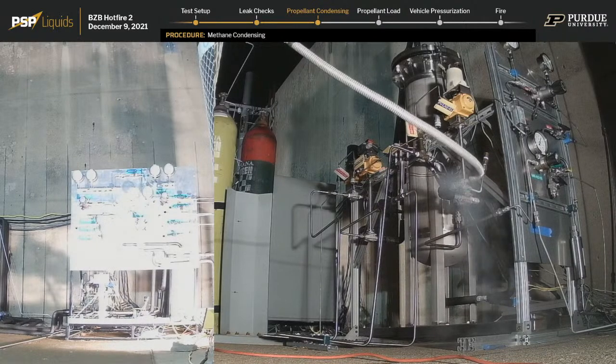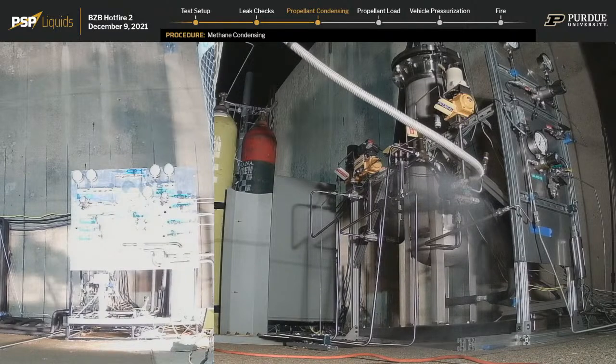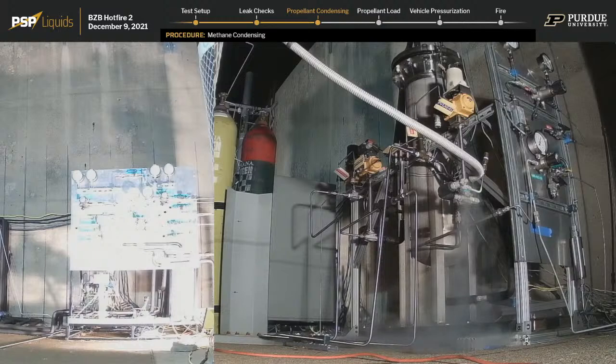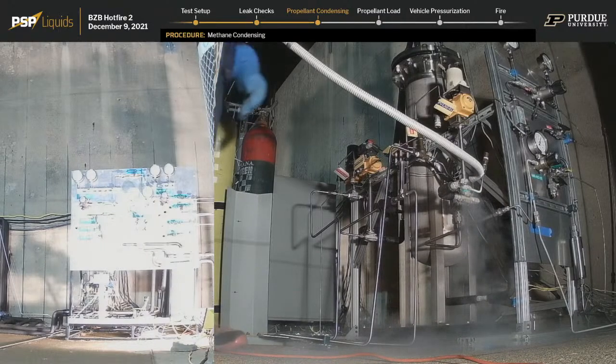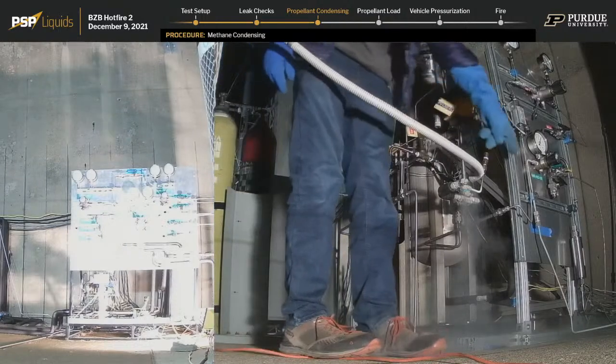Okay, we went ahead and opened PVLN201 to begin LN2 transfer to the condenser again. Believe you can hear it now. The LN2 flowing, hopefully not flowing out the dump valves anymore, but now we're seeing some of that ice forming and the clouds that we were expecting earlier. You can see the lines are turning white here, and that is definitely frost forming on the outside. This little bit of condensate, or the clouds forming, may be a slight amount of leakage. However, given its position in the system, that's acceptable for us. Right now, this is just bulk nitrogen that we will be constantly flowing through and out the condenser to keep it right at the temperature we need.